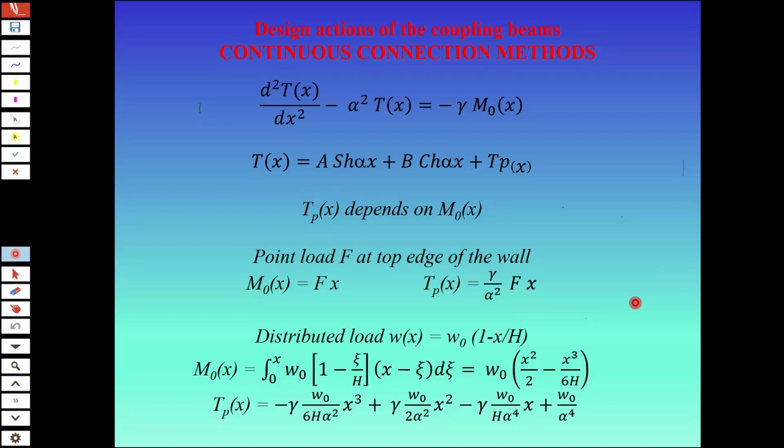You use some very simple pre-design equations. For a column, you easily can have the axial load on that. Divide that axial load by the design strength of concrete. You find the minimum area of concrete size that you need. And if you have the cross section of the concrete, you know also what the minimum reinforcement will be. So you already have an idea of your concrete properties.